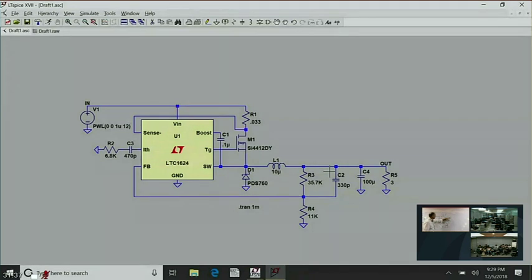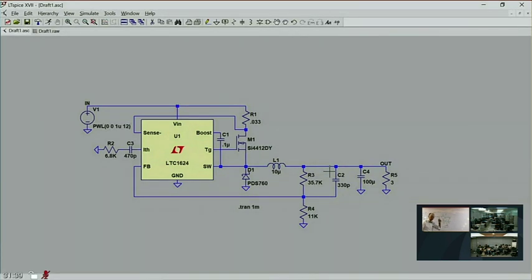If this is shorted to ground, you turn the switch on, you have this huge voltage across the inductor, and the current ramps very fast, and it might overshoot the peak allowed current through this switch over that minimum on time. But say the output isn't connected to ground. Say it's 1 volt. You still have this abnormally high voltage across the inductor, and it still ramps very fast, and it might overshoot. See, the thing is, when the switch is turned on, the inductor is connected between the input and the output. If the output is abnormally low, you have an abnormally high voltage across the inductor, and that's when you want to go into frequency foldback. Okay. Anyway, that's the way it's implemented.